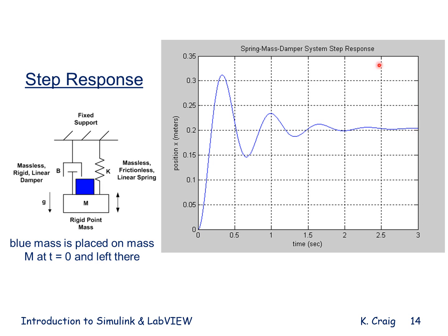And this is the prediction of the step response from MATLAB, Simulink. And I would compare this to the measured step response from my ultrasonic transducer, make that comparison, and then decide if my model is adequate or not. And if it's not, I then need to revisit my simplifying assumptions and make some modifications.